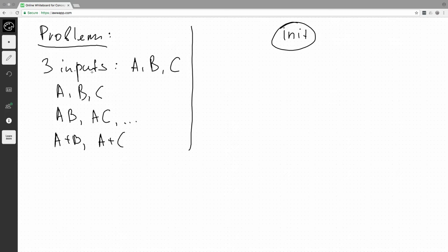The big difference between the two types of finite state machine, Moore and Mealy, is that usually a Mealy finite state machine, the one that allows output to be changed not only with respect to the state but also with respect to the input, requires a smaller number of states, because we can keep the same state and change the output when the input gets changed.